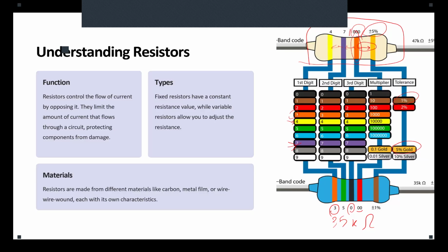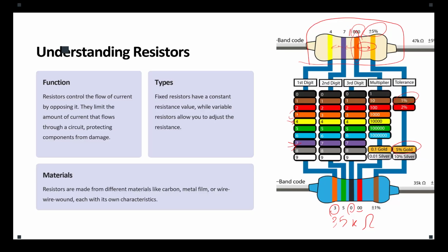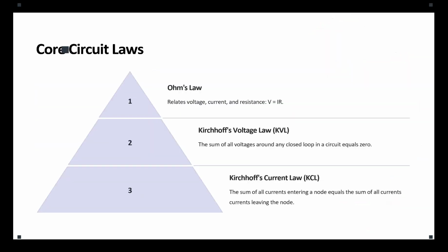So this is the way you can read your resistance. I think the first task in the lab assignment is reading such numbers and then measuring them in the lab to see what the meaning of that tolerance is and how close one resistor can be to the nominal value. Okay. Now, any questions so far about the resistor or how to work with the color band? No? Are we good? Okay.